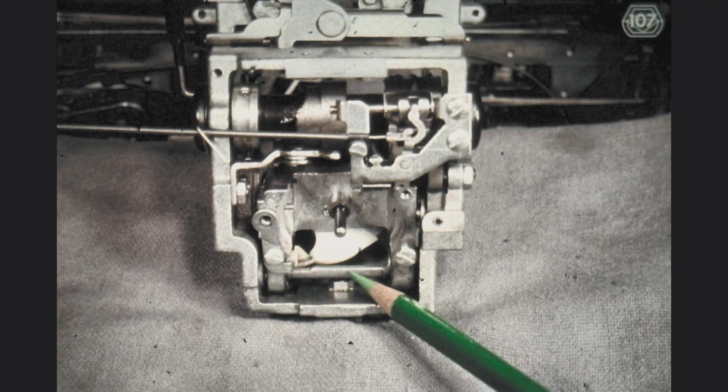Again, be sure that you choose the correct tool for the set screw, which holds the rotate pulley in place. With the rotate pulley out of the rocker, we discover that the tilt tape pulley also extends into the pivot shaft of the rocker, which has been cut in half at the point indicated by the green pencil. Obviously then, in order to remove the rocker shaft, we must also remove the tilt pulley.